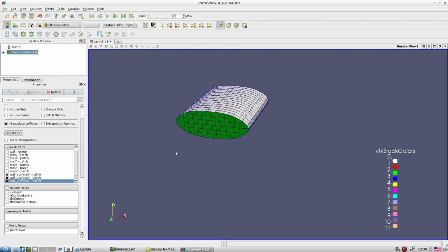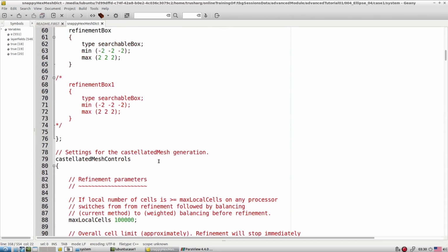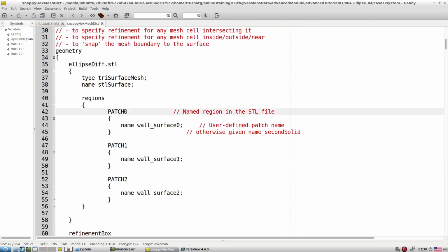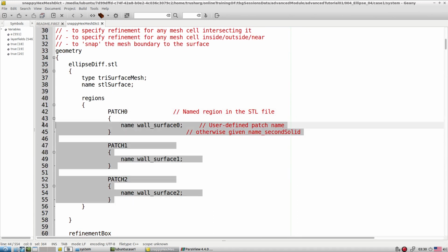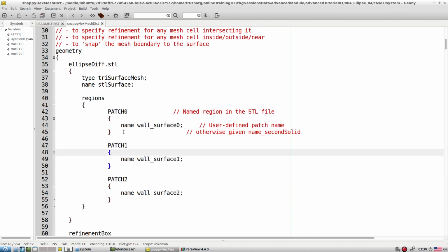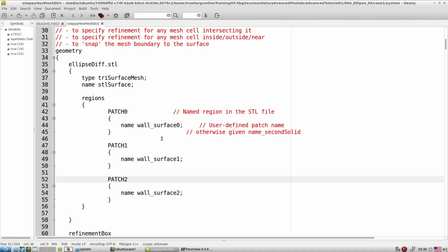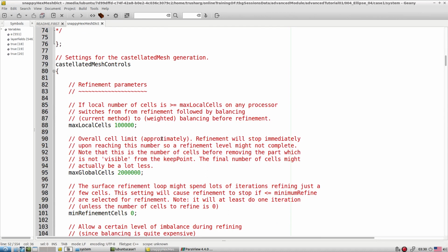This is very straightforward, but make sure you have separate names while creating the STL file from the geometry. Inside the geometry you give the separate names, and based on those names you will see all the required information inside the STL file. Then you plug that zone region into this geometry area, and you have better control.